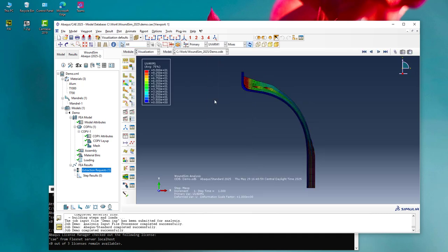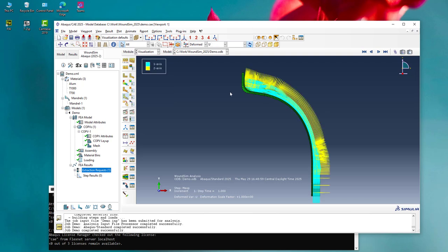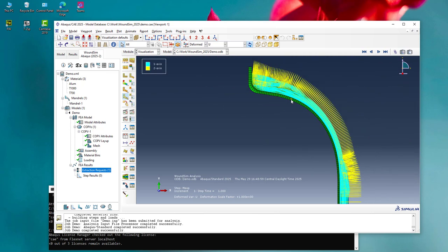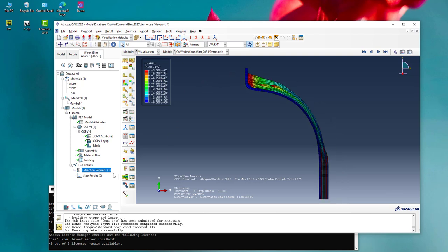So we have all these UVARM variables because we have all these orientations that are out of the plane, but we've transformed our material properties. See, if you look at these, these are our material directions. The blue is in the one direction and yellow in the two. Well, these are not in the fiber direction, so we've got to transform those global stresses into our fiber directions. So we do that with a user subroutine. So we have all those stored, and a good way to